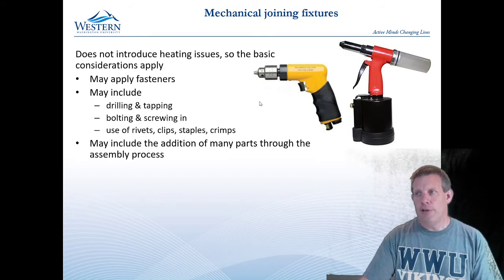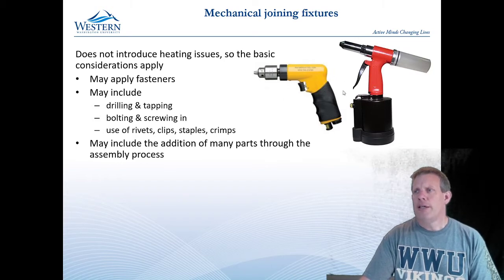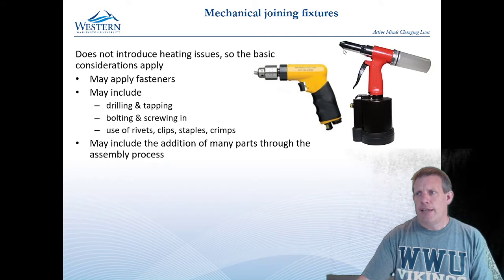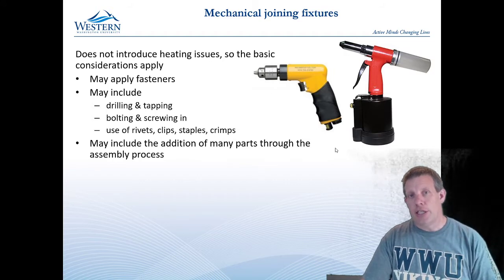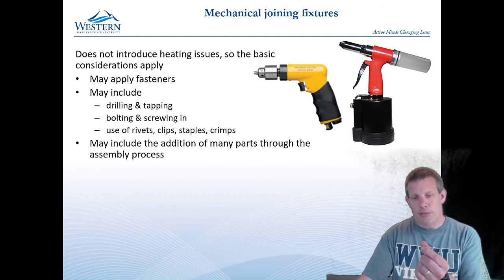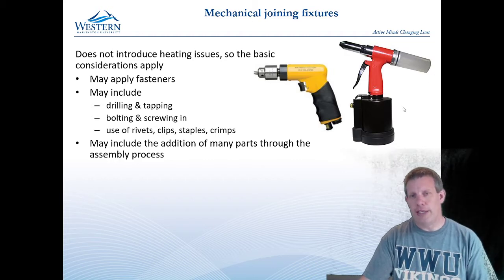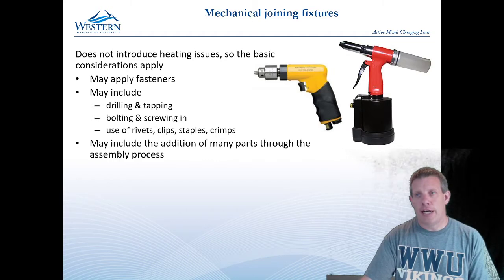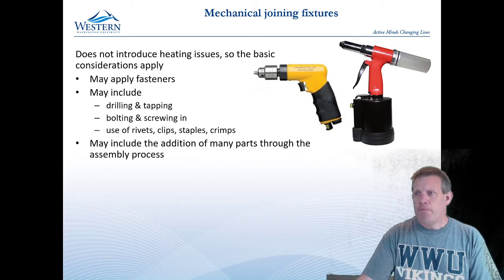This on the right side is a rivet gun, and so if you're putting in rivets, this is for pulled rivets. This gun has about a 3/4 inch nozzle on it, but you can see that the gun is really large overall. This down here is for collecting the center studs that get pulled out of the rivet when it is pulled together to squeeze the two pieces of metal together. And then on the back it has this muffler to let out the exhaust stream from the compressed air over a big area so it doesn't blow in your eye and blow chips in your eye. But these are pretty large.